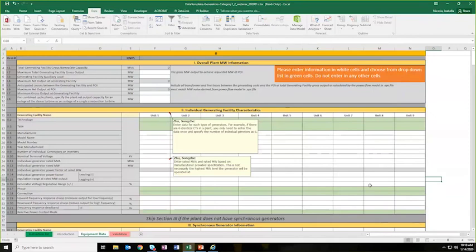Okay. So am I correct that 2.14 is based on the capability curve? No, actually it's not. The -1 means that's unity power factor, right? Yeah, but if it's unity power factor, probably your test report and manufacturer data will be the same. So this is meant to enter your manufacturer data sheet data, manufacturer specification data. What, when the equipment comes out of the factory, what the manufacturer says it's capable of.